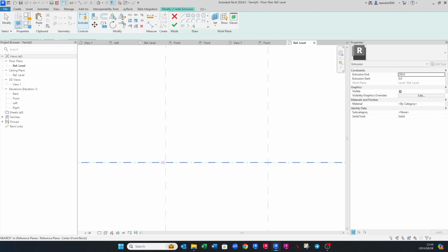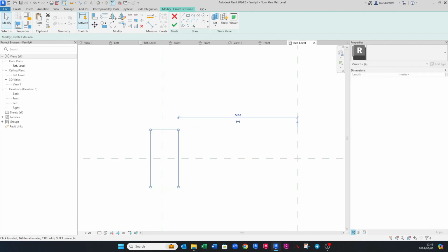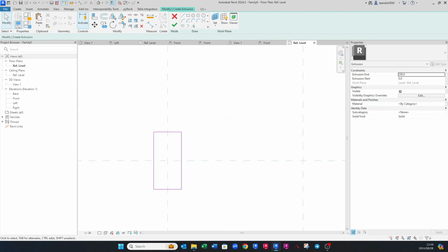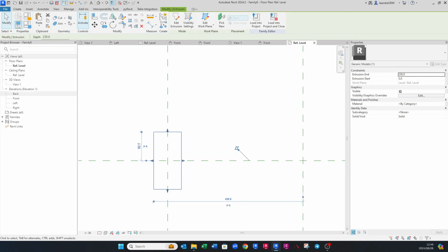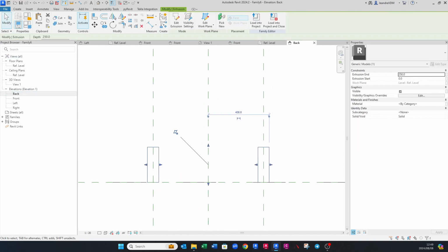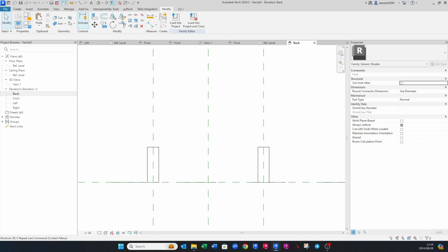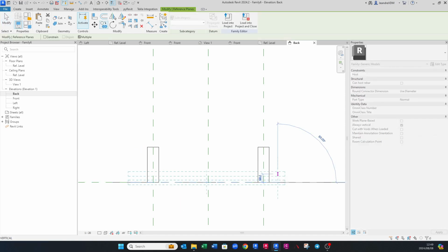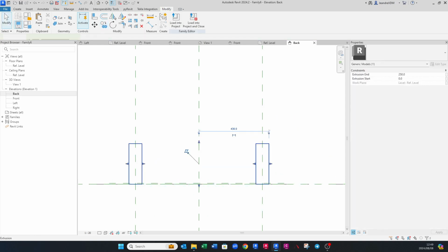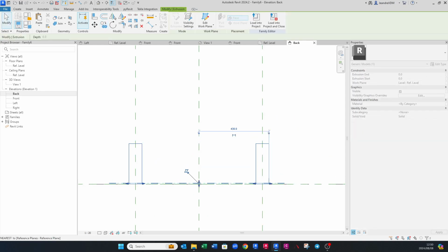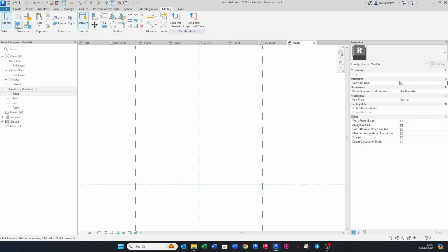I want a rectangle here. That I want 165 and already 80 mils, which is great. The other direction, I might move a bit fast, but it's exactly the same procedure. It's just in a different plane. So reference plane, that to be 6 mils. So we can lock it there. Okay, there we go.